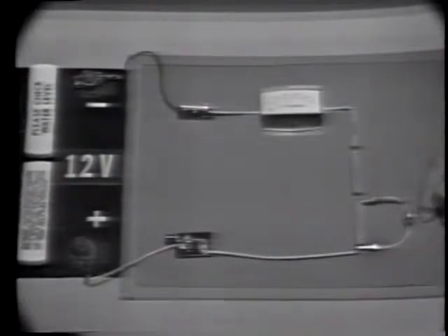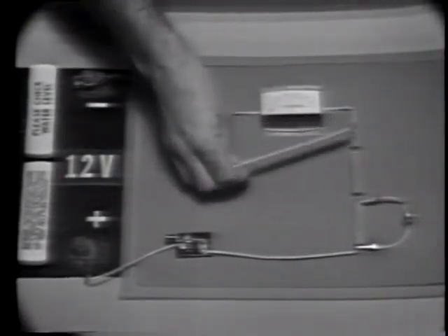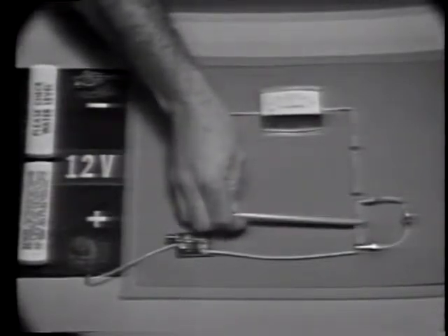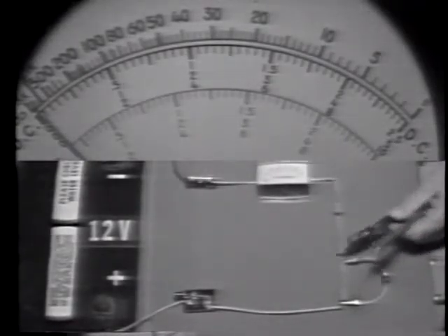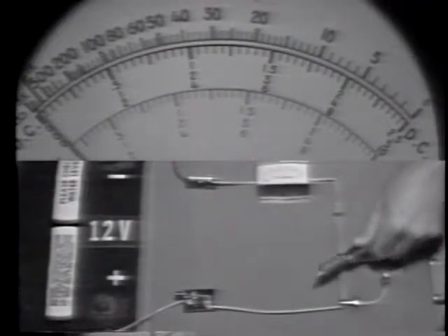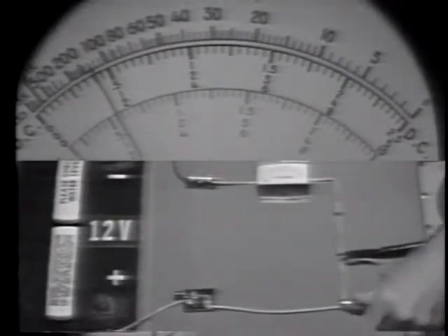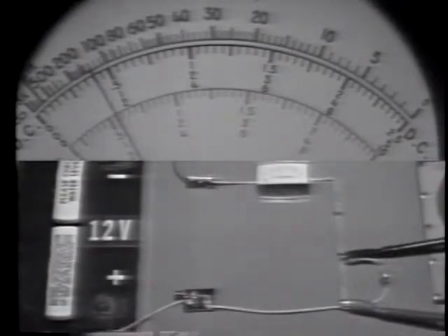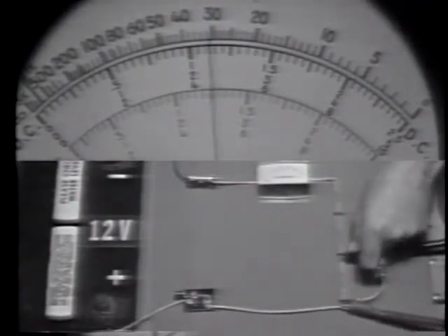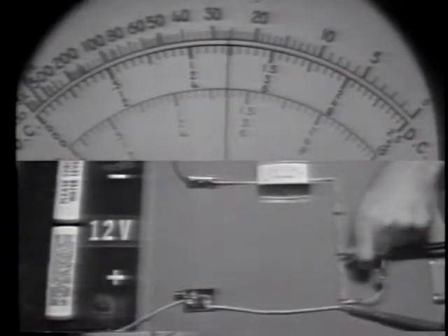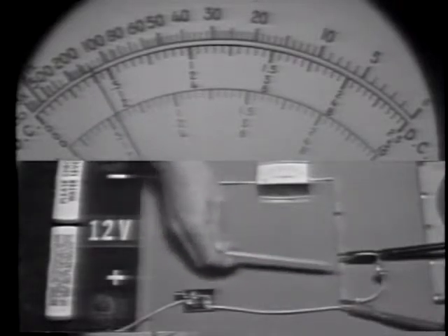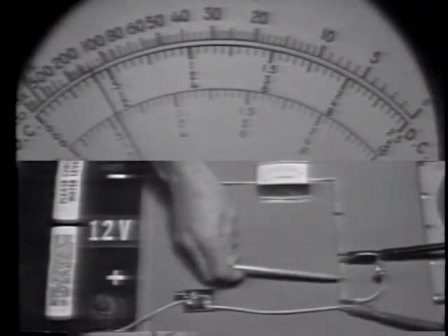Now, this current or load creates a problem. It changes the voltages developed in the divider. For example, let's use the voltmeter to check the voltage across this resistor. And of course, I must observe polarity. So connecting across this resistor and the load device, we find that it's less than 2 volts. Now remember, we're using the 10-volt range on the voltmeter, and it's less than 2 volts. Now watch the reading as I remove the load device. It increases. It's about 5 volts. When I load the circuit, the voltage across this resistor decreases to something less than 2 volts.